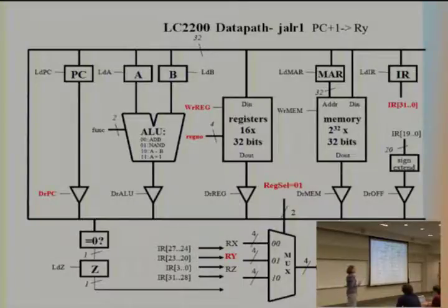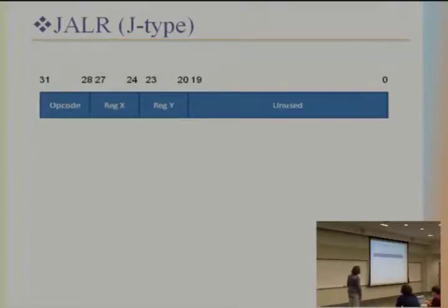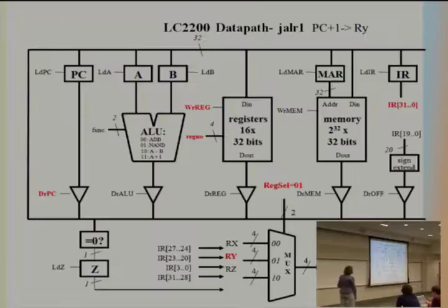Yes. Exactly. Now you have to remember that, because if you're doing this manually, like you have a homework or something, if you perform the fetching and you already incremented PC and now you want to execute the instruction, remember that PC is already PC plus 1, so don't add one more. It will become PC plus 2 and mess up everything. So PC plus 1 needs to be stored in RY, because that's the definition of our instruction.